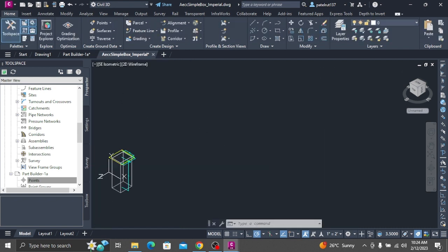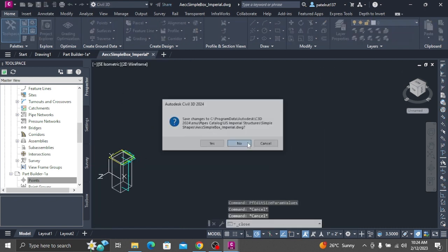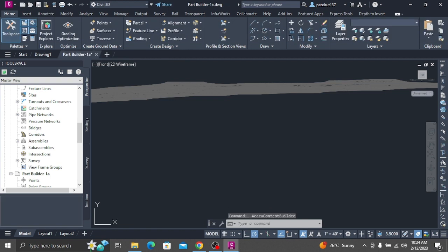Right-click Size Parameters and then click Edit Configuration. Click New. The new parameter dialog box is displayed. Click Frame Length, and then click OK. Click New, then click Frame Width, OK. Two new parameters have been added, Frame Length, SFL, and Frame Width, SFW.